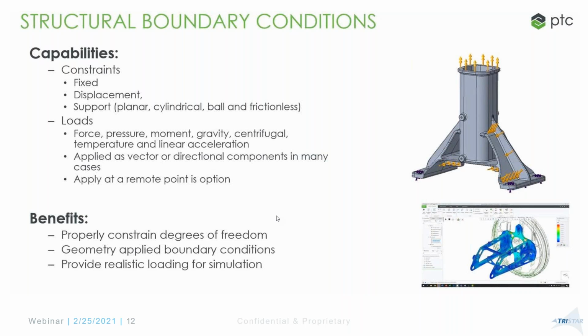Right? You can also apply a load at a point and then distribute it on a surface. Very useful during my industry days. I used to use it a lot when you simplify a large assembly wherein you really don't have to have the full load path. You know mathematically the magnitude of the load and where it's applied, but you're more interested in certain other areas based on the load path.